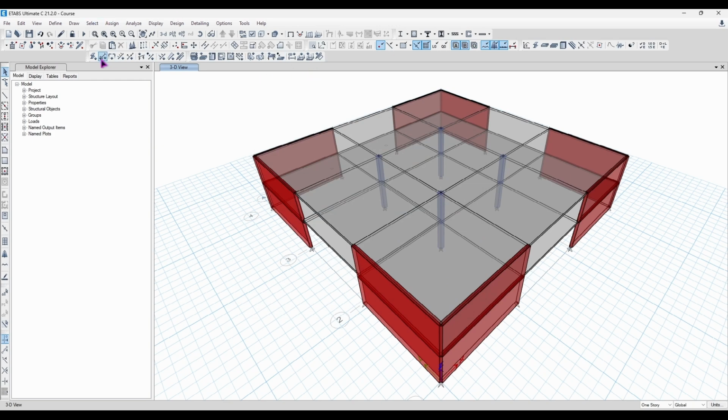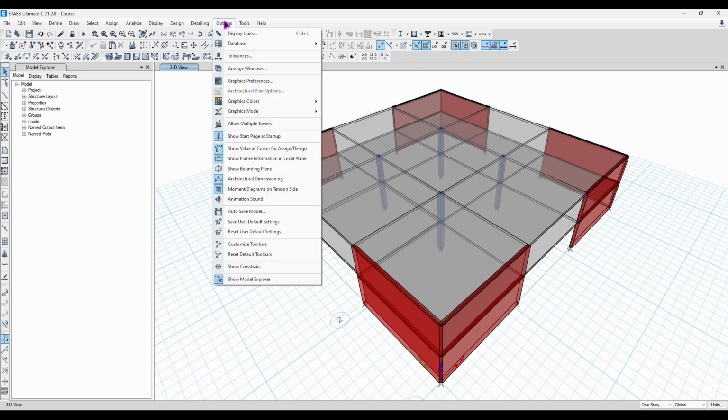I don't have to go to the edit menu, right? You can click, you see here there is a little kind of a teal color edge. You can hold and drag to change the position of the ribbon. So this is like the define material, right? If I click on this, I'm defining the material. I don't have to go to define. This is the draw menu. This is the snap option. This is the selection menu, a little bit of it, not all of it, of course, and so forth. So it's a really cool tip.